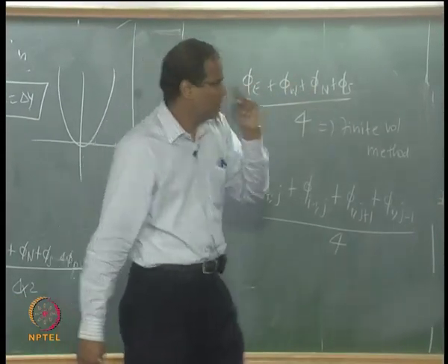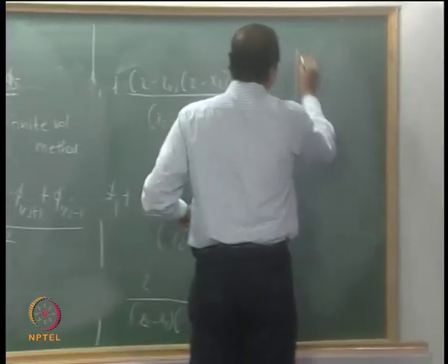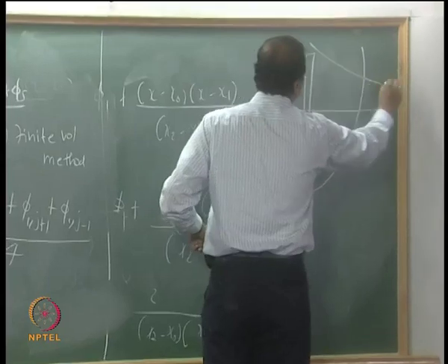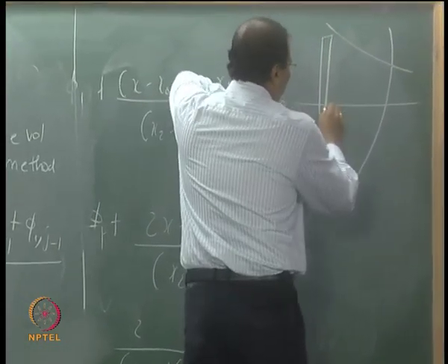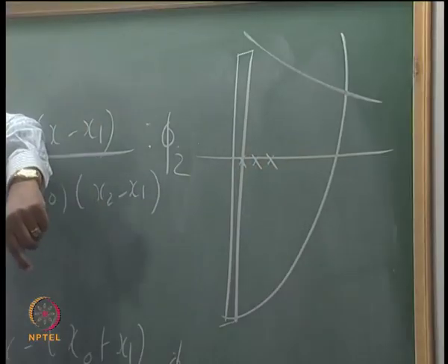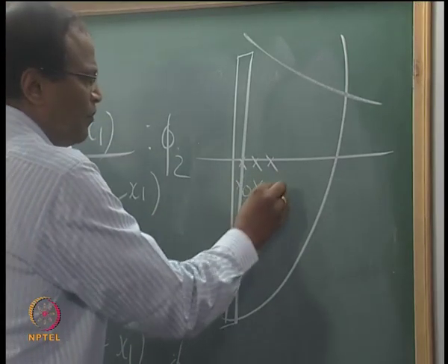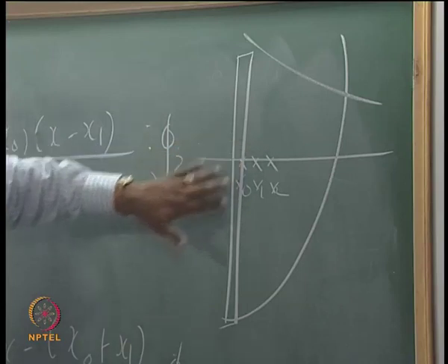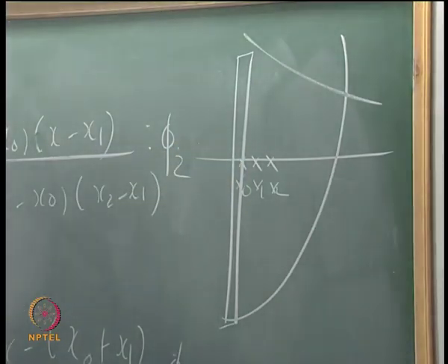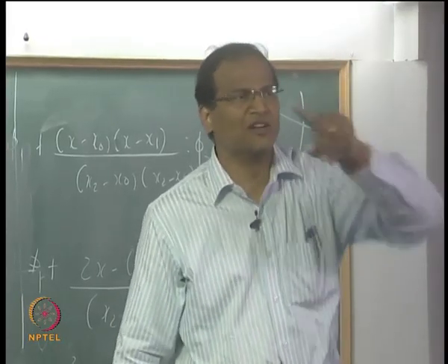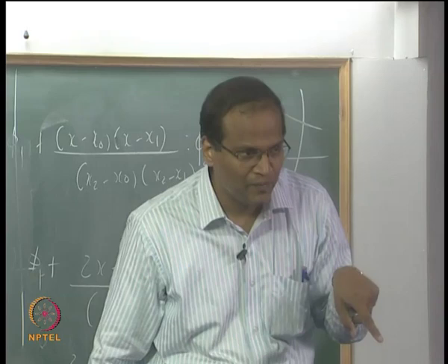So to round off the discussion, for example, if you have a boundary layer which is developing like this and you want to measure the temperature, you can take your anemometer and get the temperature at 3 points, x0, x1 and x2. Using the second order Lagrange interpolation formula, you can get a better estimate of the gradient rather than taking x0 and x1 and computing dT by dx as T1 minus T0 divided by x1 minus x0.